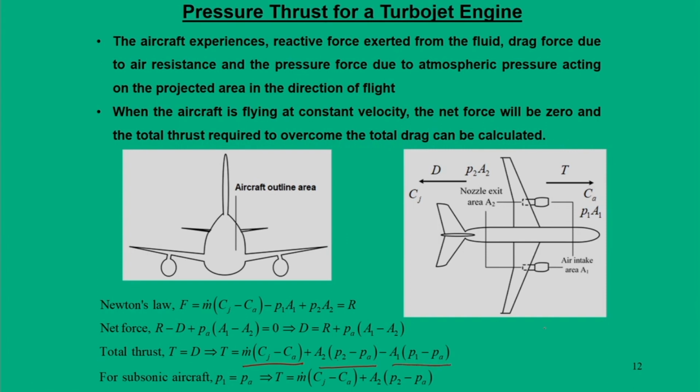So, where Pa is your ambient pressure. And for a subsonic aircraft, I think the second term does not appear, because there is a different concept that comes in, that is the formation of shock waves; there are no shock waves in the picture. So this particular term does not appear for the subsonic aircraft, but for the supersonic aircraft the entire flow which is outside this medium also gets disturbed. Because of this reason this particular term remains.